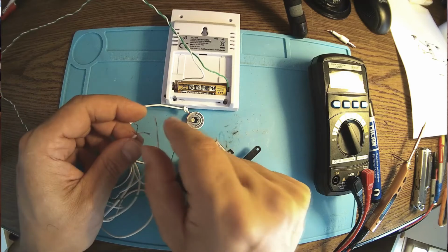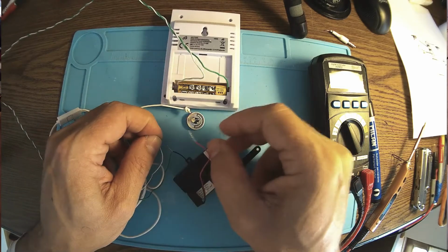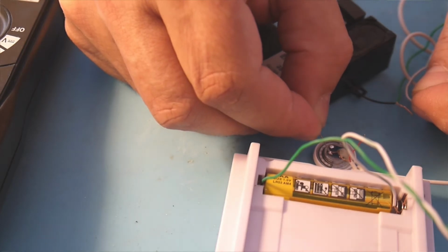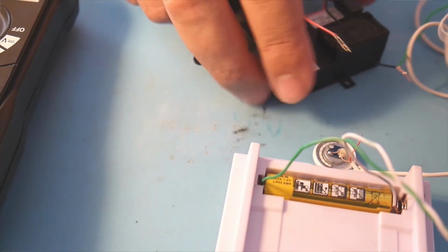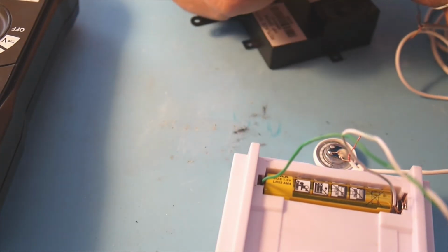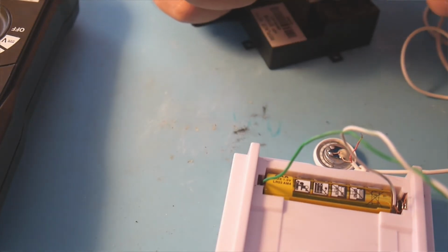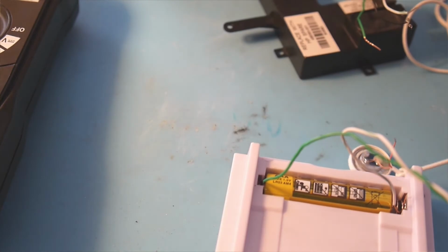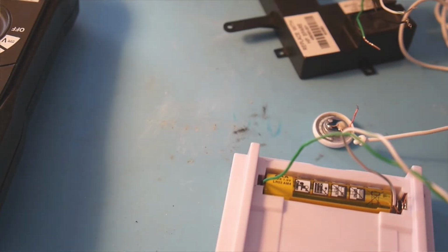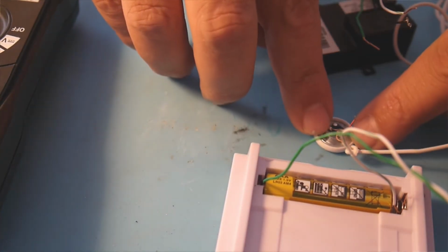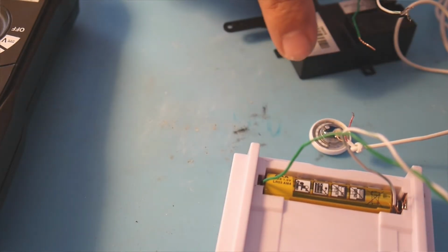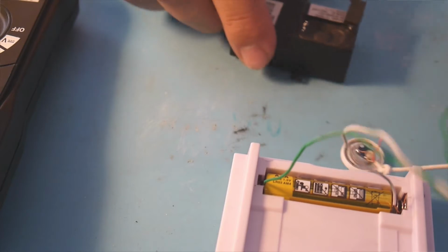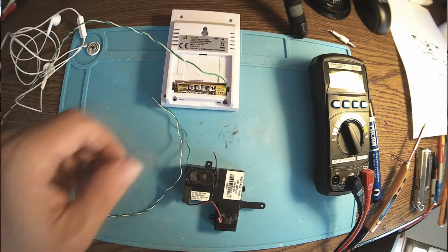Now let's go to the yellow and check it here. So the yellow is good. In our case, the wires are good, so there is no problem with the wire. If we don't have sound, that means the headphone itself is broken, burnt or something. If we have the sound here, but nothing through the wires, that means the wires are bad. And this is a very simple way to improvise a measuring tool.